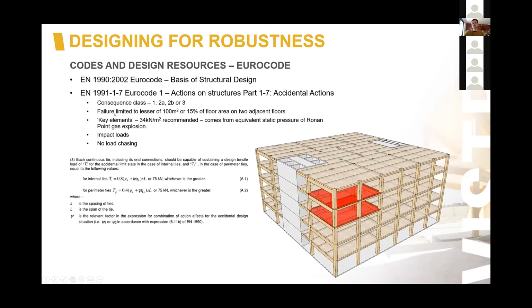I mentioned the consequence classes. Generally in the Eurocode, I think it changes for certain national annexes, but generally speaking, it gives some guidance on what disproportionate collapse is and limits the extent of failure to the lesser of 100 square metres or 15% of the floor area. So if we take this example here on the right, that's a 9x6 post and beam grid. You could have localised failure of 2 bays across 2 adjacent floors,